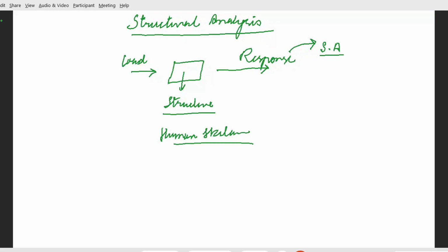We have to take care of loads which will come because of environmental constraints, like the snow load, which many regions in, let's say, India, don't have to take care of. But here in our region, we have to take care of a number of things. Like I said, being a highly seismic prone area, we need to see what amount of cyclic loads can come due to lateral loads, which is seismic loads, or even wind loads.